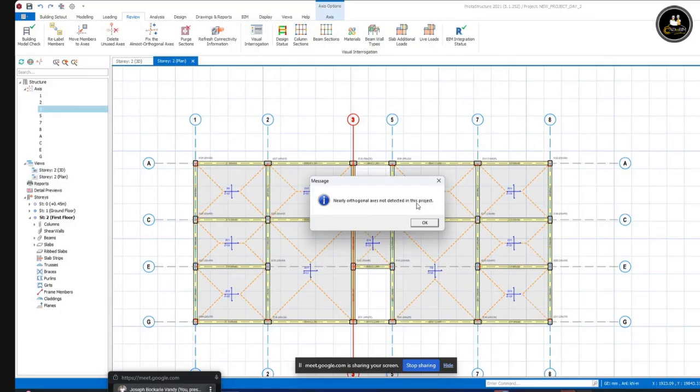It's a bit slanted. When you see it with just eyes, normally you can think it is actually at 90 degrees, but it has slightly diverted from 90, so it can be brought back to 90 degrees. That's when maybe you are drawing and you didn't use the control button to ensure that all your axes are straight. So you can just click OK, then we proceed.